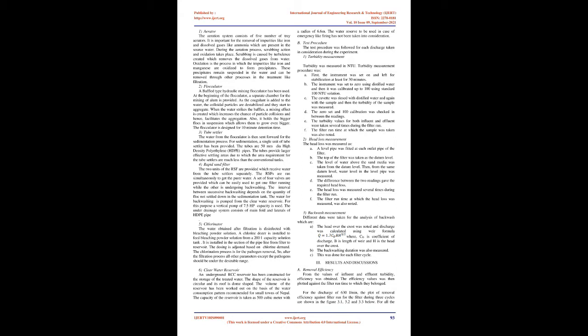RSFs are incapable of providing safe drinking water without adequate pre-treatment and final disinfection. Due to this reason, usually, coagulation and flocculation, and chlorination are applied in the water treatment systems.